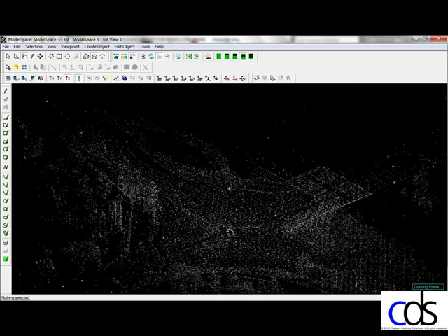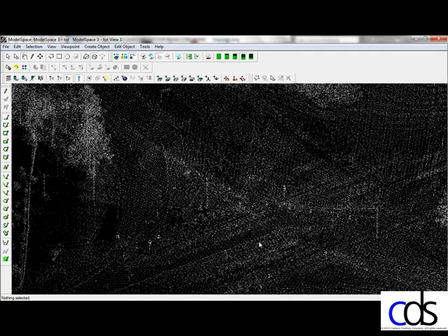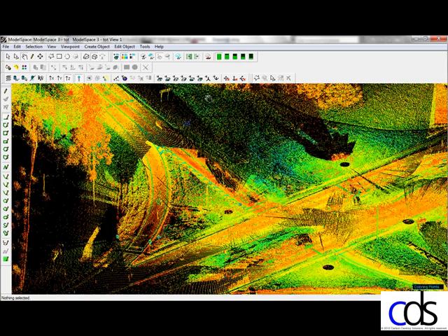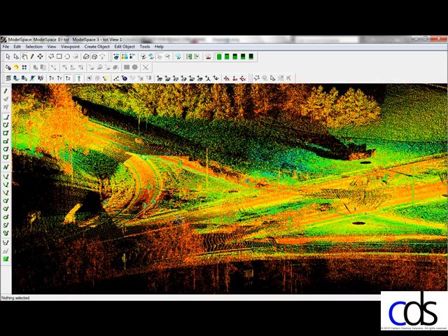If we were to go out and survey a site, we would collect individual locations of various components of the site, such as the locations of individual utility features or of planimetric details. When we go out and we scan, we're collecting every piece of information that's there. Now, this information can be overwhelming. If we look at the example here, we have tons of data.